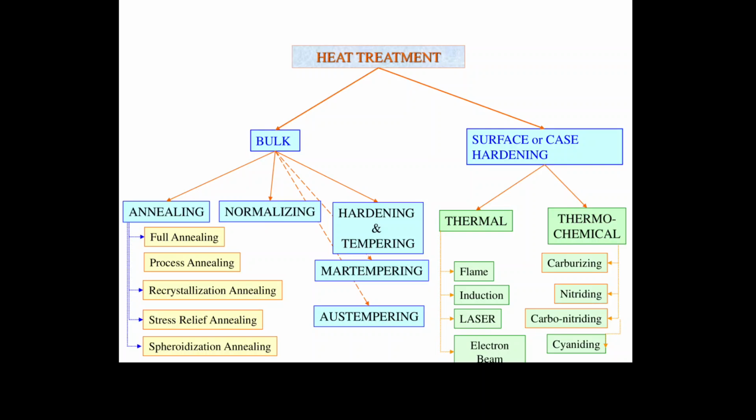Then there is the tempering process. This process is only done for hardened steels. These hardened steels, as already told, are brittle and very hard. Such hard materials are difficult to machine, and because they are brittle, they are easily fractured. So to improve the fatigue strength, the tempering process is used. In tempering, the material is reheated and then slowly cooled at room temperature. There are two different purposes, depending upon low tempering temperature and high tempering temperature.